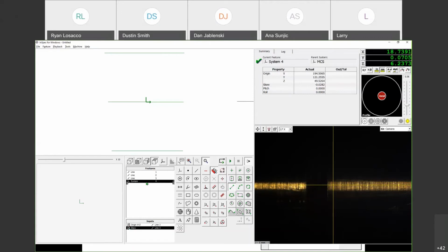So I'm going to go ahead, I got my system. I'm going to rename this to being my system XY. And if you were in the January webinar, we talked about measuring radiuses, and we talked a little bit about measuring chamfers using flip working plane. It's something that is uncommonly used because it's pretty advanced programming. So I might hit flip working planes a lot for you guys to learn more about it and the cautions to take while flipping working planes.